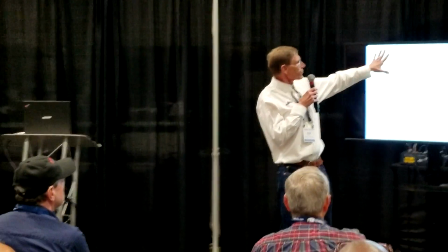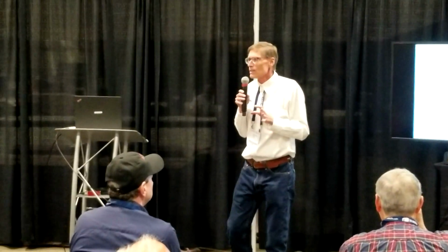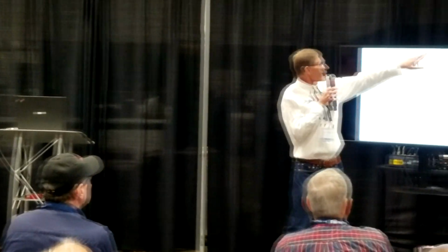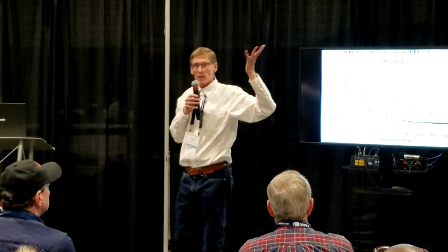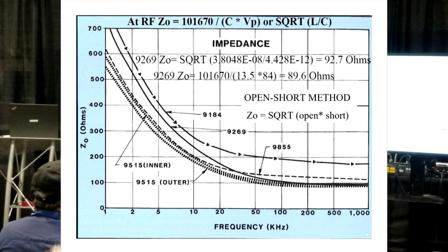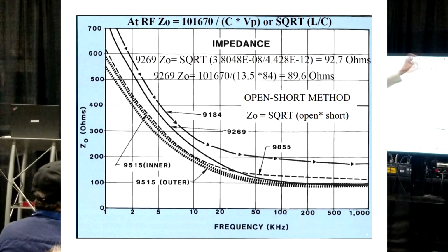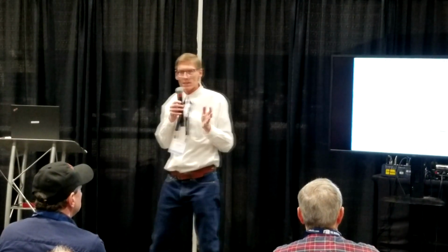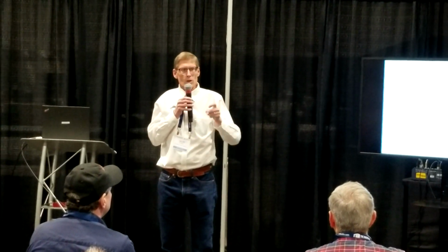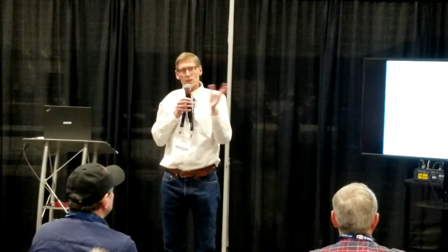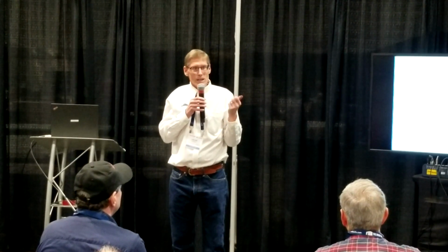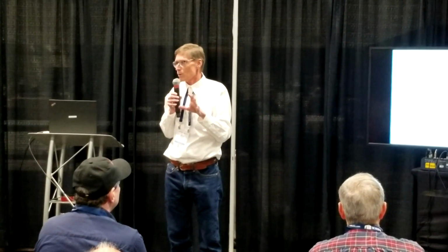These are some examples of a couple of cheaty little easy ways to determine what the impedance of a cable is. If you look in the Belden catalog, we'll measure the capacitance for you and tell you what that is, 17.3 picofarads, whatever it is. It's measured at 1K, it's going to be the same at RF. We'll also show you what the velocity of propagation is in that particular dielectric. But to do that, you have to have some really expensive equipment and do what's called the resonance method. Basically you put in two different RF frequencies and do some tricky math, and it will come back and say what the velocity of propagation of that particular dielectric looks like in that cable, and we'll put that in the catalog.